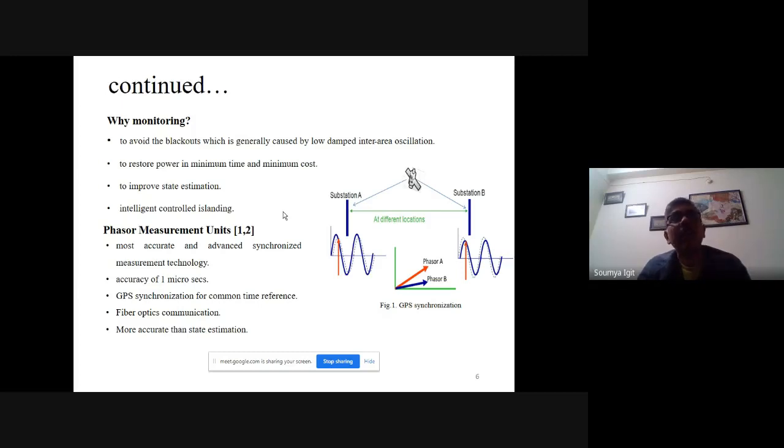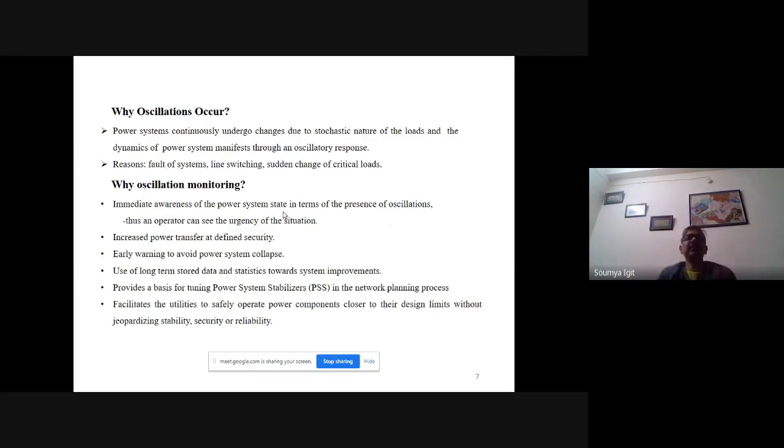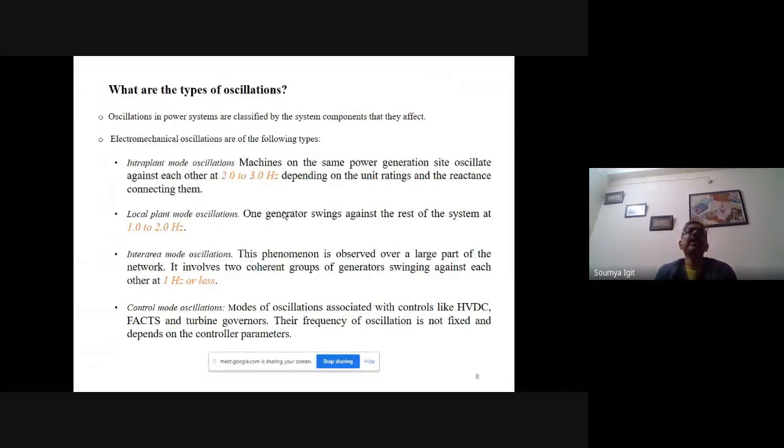A similar scenario also prevailed in Mumbai. If you go for a thorough simulation analysis, in a steady state power flow scenario subjected to any contingency and any fault, and you introspect the system behavior and cross-validate it, had the PMU been deployed at strategic locations, this catastrophic failure might have been averted. That is the point of interest for a comprehensive analysis. The oscillation mode I have already discussed before,